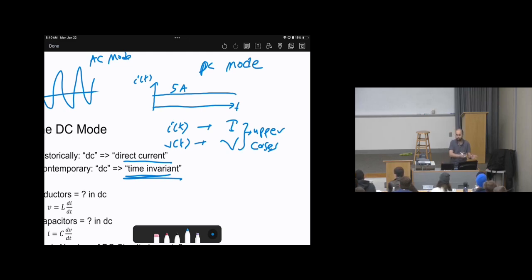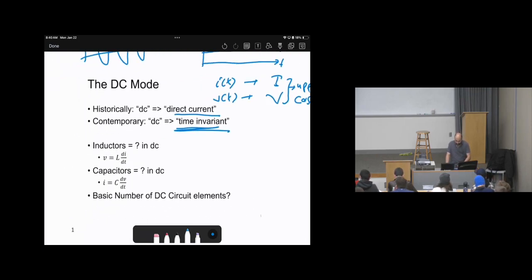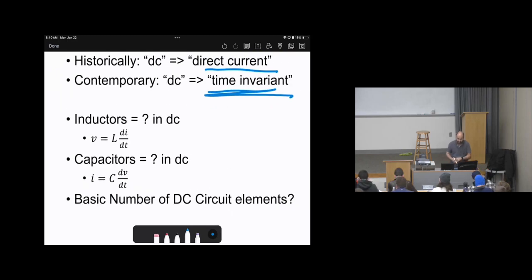So the only thing that you are required to know about AC is what you have learned about the circuit elements by applying Ohm's law, or resistor or inductor or capacitor. Otherwise, everything is in DC. Let's recall V equals L di by dt. And in DC, I is constant, and again we will call it I, uppercase. So this will be L d by dt of the current I. Since I is constant, it will be 0.